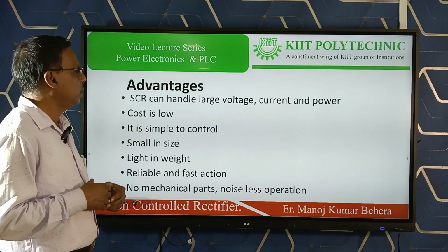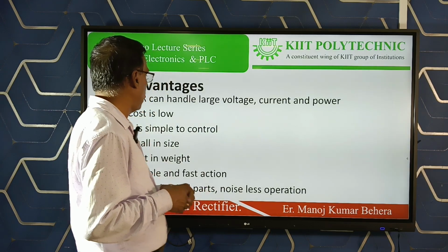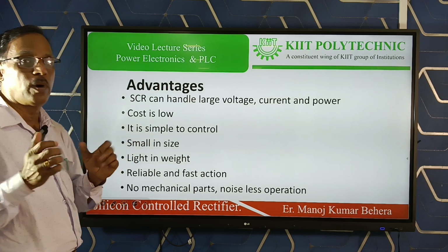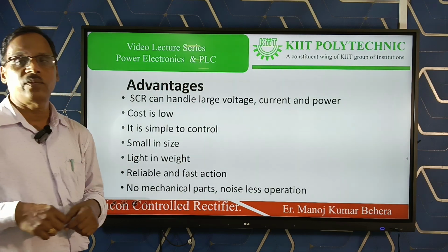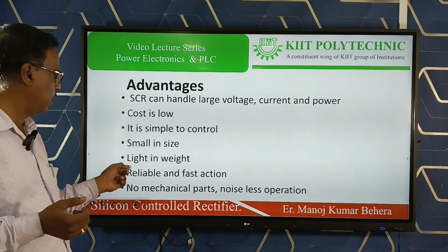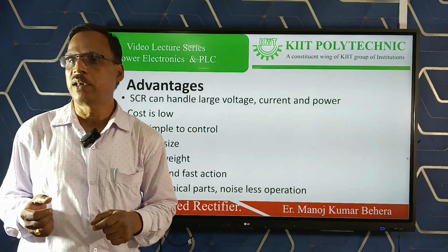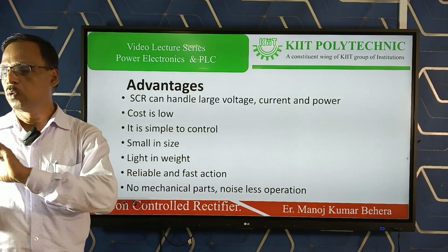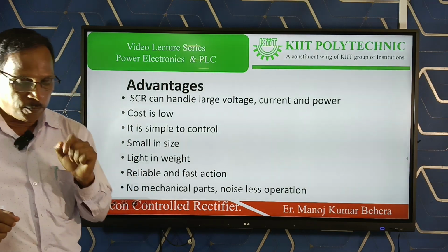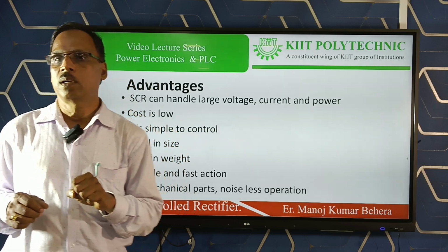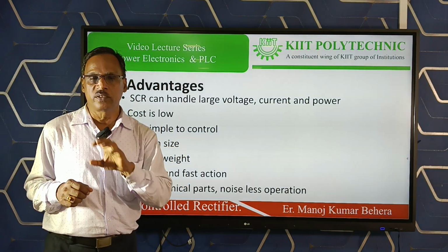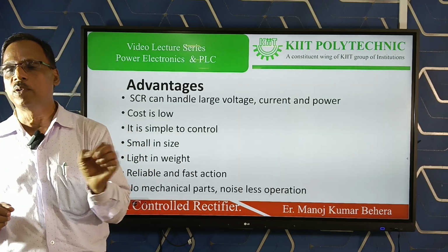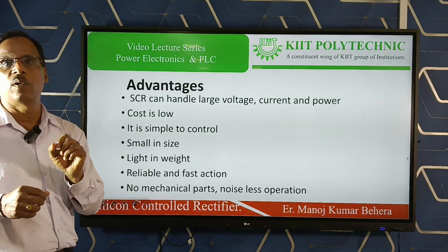It can handle very large voltage, current and power. The cost of SCR is very low. It is simple to control, small in size, light in weight, and reliable in action. No mechanical parts are there, so there is no noise. In power electronics, most converter applications use SCR because it is light in weight, reliable in operation, and can handle very high voltage.